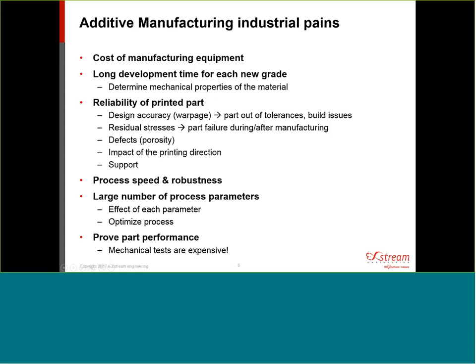Behind this warpage, there is also the notion of residual stresses. Those residual stresses are very important to consider because obviously they will have an effect on the part performance. You can have part failure during the printing process because of too high residual stresses, or you can also have preferential failure after the printing step because of very high residual stresses.